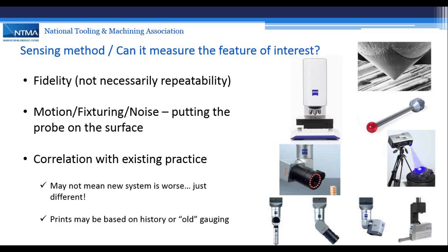That doesn't necessarily mean it's repeatable. The most repeatable gauge could be the dead one. Pull the plug, put a big fat tip on the end of it, and it will repeat. Desensitize. Desensitize, a great point. So if we desensitize a gauge, sometimes to get repeatability, you would never do that. So the gauge with the most sensitivity may not be the most repeatable. And that's a challenge, but it is a true fact.